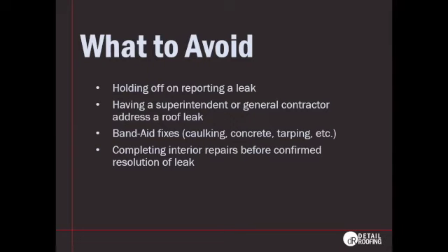And you would want to wait for whatever the weather event was that caused the leak in the first place. So if it only happened during wind-driven rain, or if it only happened when snow was melting, then you'd want to wait for that to occur again to confirm that the issue has been resolved before spending the money on the interior repairs.